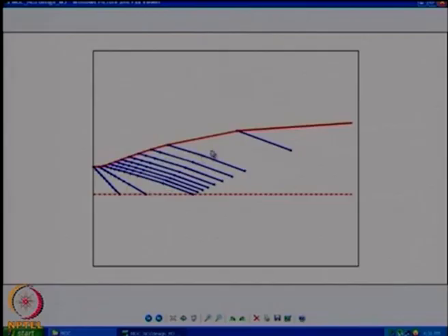This line is going out there, while the next line, the last line, is expanding all the way out up to here. That is also expanding, but when they hit the compression wall here and come back, they are coming back almost parallel by the time they reach this point. This expansion going out this way is countered by this compression this way for each of the characteristics, and they finally become parallel roughly when they come here. When the characteristics are parallel, you are going to have a uniform flow field. When the characteristics are expanding, you are going to have increasing Mach number. When the characteristics are converging, you will have decreasing Mach number.